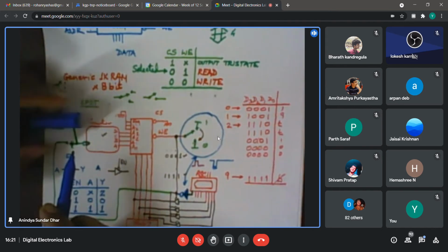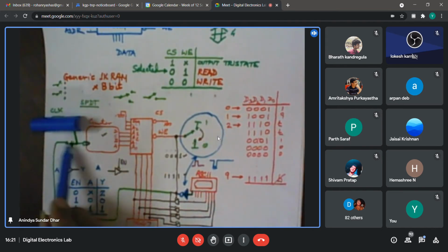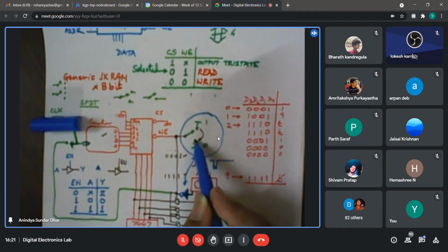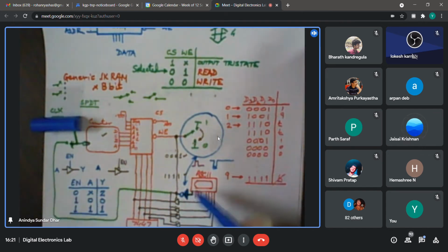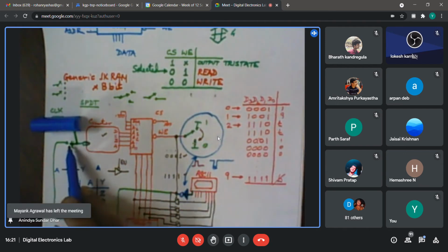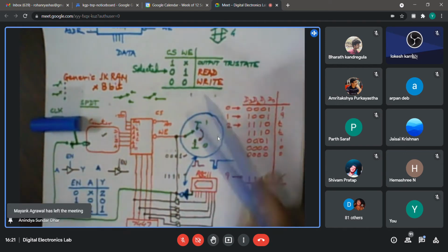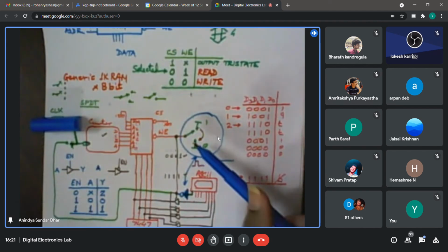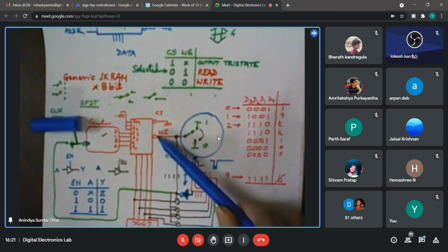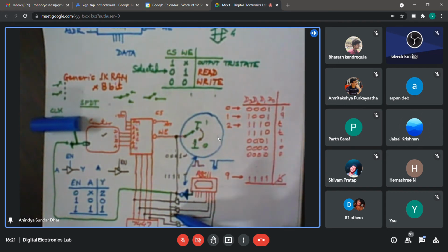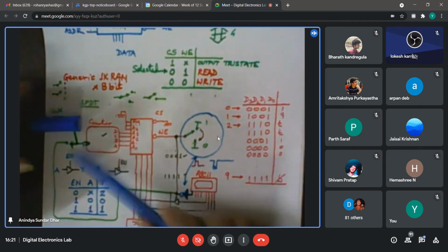At that time I assume that you do not have any pulser. So this is directly connected to the clock signal. So either through this switch, by throwing the switch off and on, you can generate a clock signal. Or else, as you are suggesting, maybe I can use that inverter and generate the clock signal. But once again, I would suggest that whatever you decide, do it from the same signal. Either you use this or you use this. So your write enable, this enable for the buffer as well as the clock, you derive from the same source.